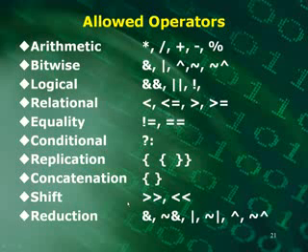Like in my case, the real RTL code was the one-wire transmit, the one-wire receive, and then I have a test bench that actually drives that. There wasn't very much in what I showed you as far as driving it. It just had it run a little ways and stop, so I could look at the signals. But you could have it check. In your test bench, you could say, after it goes a certain amount of time, you might want to test the read values, make sure you're getting back the right read values, and if not, you print out some statement.